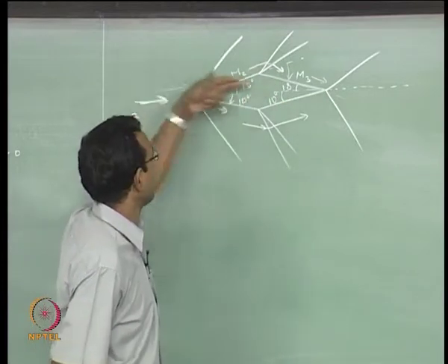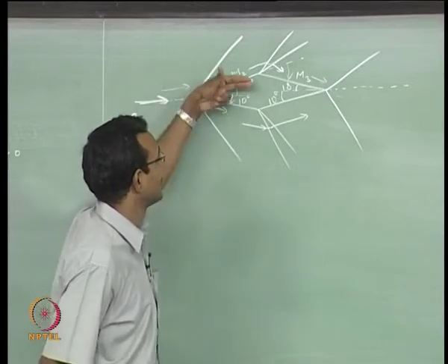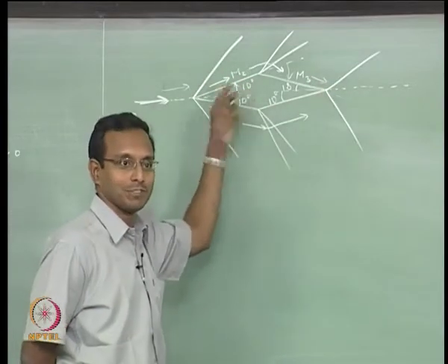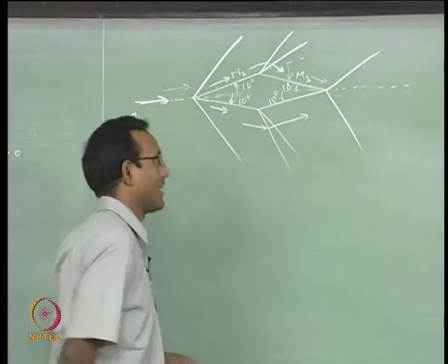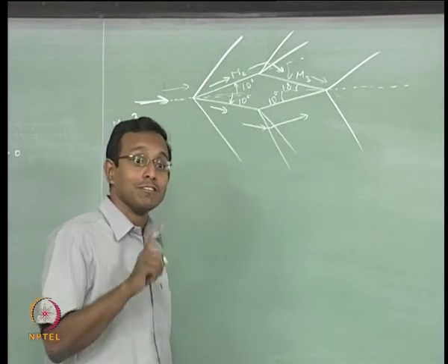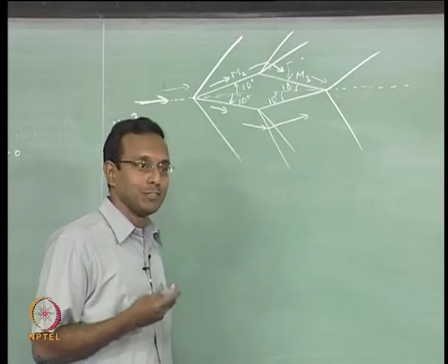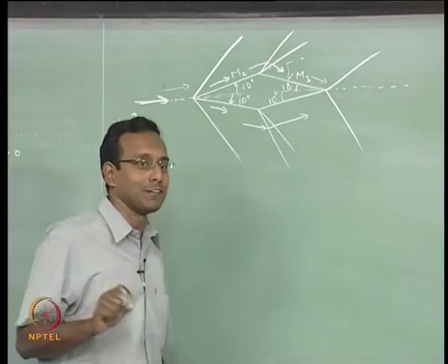If I look at the vertical, this component of the area, then I will see that this is going to push and that is not going to push back as much. So, there will be a net push this way, that will be your drag. Okay. So, this particular body will have drag even at 0 angle of attack, which is not the case for the previous problem, flat plate, where we assume it is very thin flat plate, no frontal area.